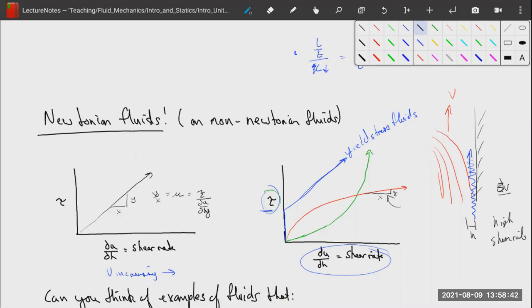But then when you take the brush away, it moves at a much slower rate because the only thing pulling it down now is gravity. And because it's moving at a much slower rate, its shear rate's a lot less, and its apparent viscosity, which is y over x, right, is much higher. And that's the whole reason why latex paint, not the whole reason, there's lots of reasons why, but latex paint is so darn useful.